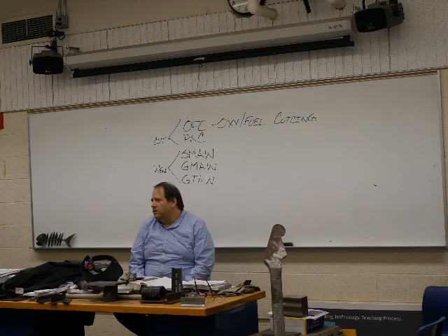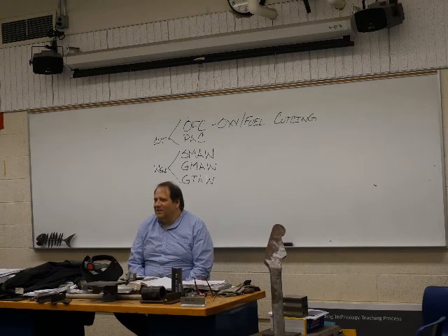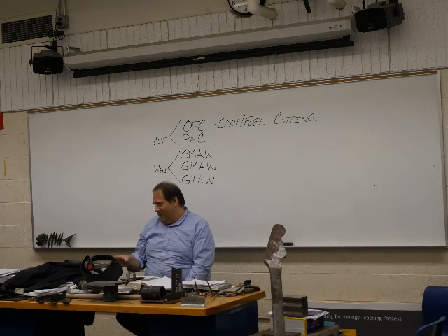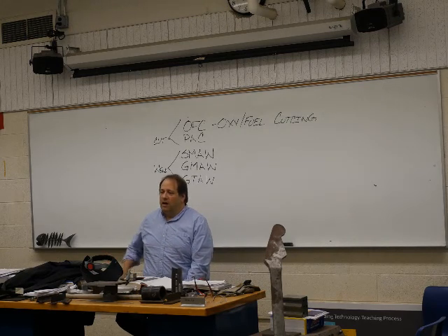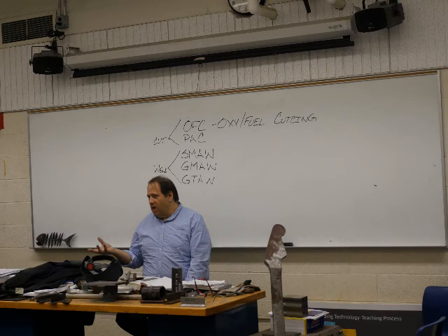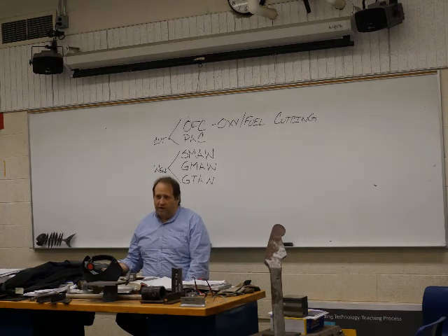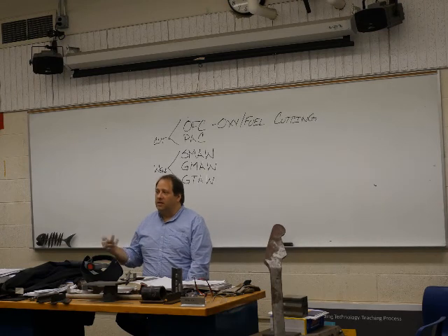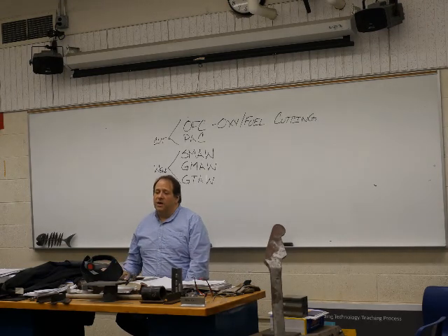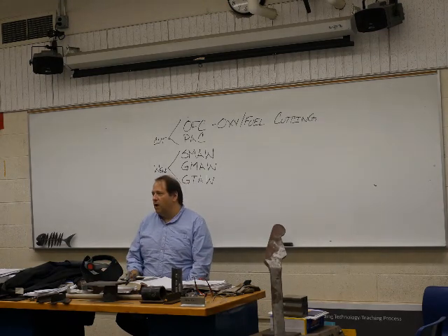Have you ever looked at an oxygen tank? It says nothing about it being flammable. It's not flammable. It's an accelerant, so you won't see anything that says flammable on it. What it's doing is taking an already open flame and making it hotter by adding oxygen to it. But it also does another thing: it creates an oxidizing process, which is actually the cut process.